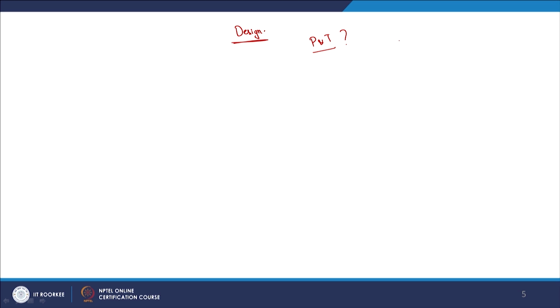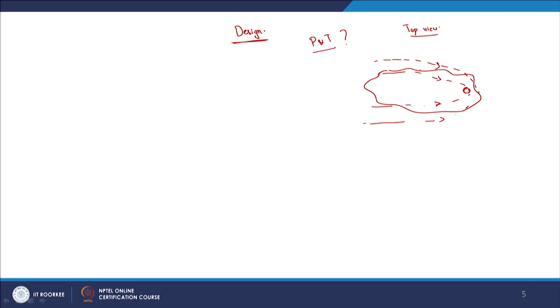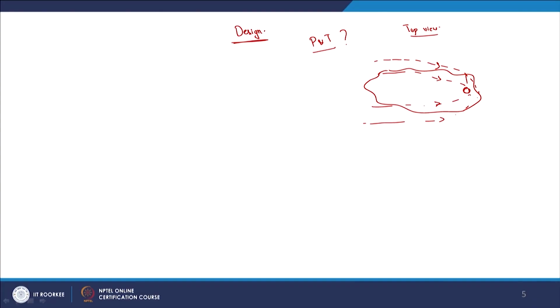If you remember, if this is the top view and I have my contaminated plume like this, I can place one well here, based on the Avendel et al. design, and depending on the flow rate I can capture this particular flow path. This is the boundary of the flow path that can be captured. So the key aspects there were that we had to figure out how many extraction wells to have, what rate of extraction we needed, and the placement of the extraction well. The placement is something we had to look at.